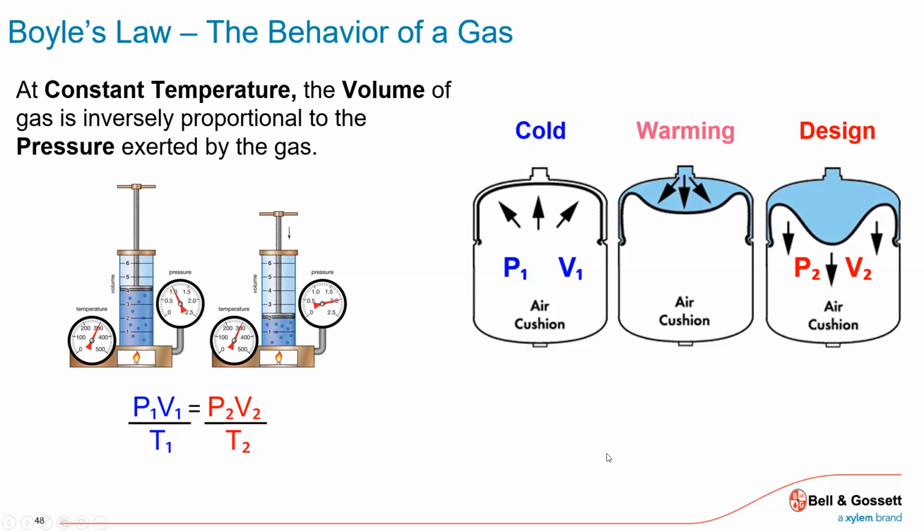So all they're saying here is, if I have the same temperature and a certain pressure and I put more pressure on, the volume has got to decrease. And that's kind of a neat little picture. It's very simple, but that's talking about what happens in an expansion tank, whether it's this little residential one or a hundreds-of-gallon diaphragm, big commercial ASME tank.